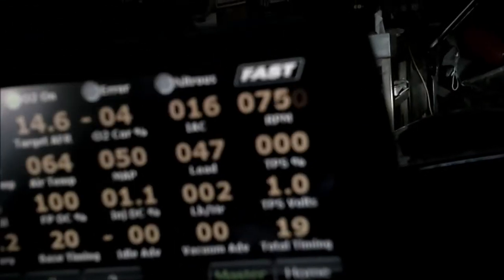Right, so this pretty much gives me everything that could be here. If I go back here, then I can go in and I can change stuff. So just to give you an idea, I could change the engine parameters. I can change the fuel system, whether it's returnless or not. I could change the fuel injector size, which I've done 3 times, putting bigger ones in. Crankshaft positioning input. Ignition timing is there. Calibrating the idle air control motor.